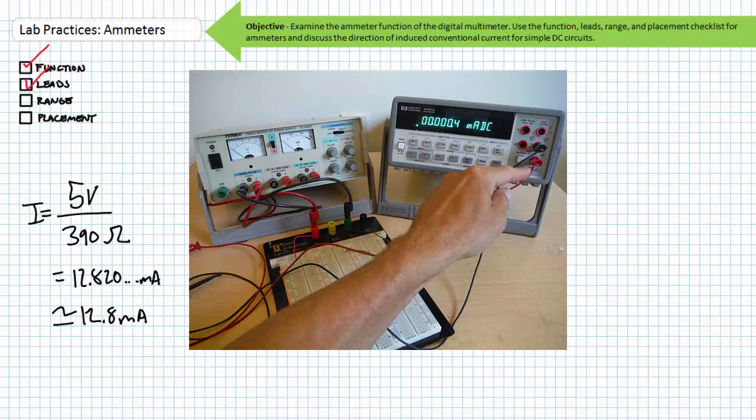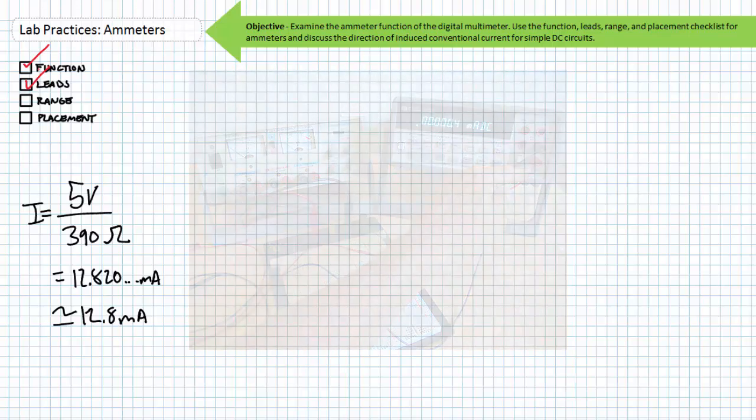Again, notice the DMM in ammeter mode is using different lead placement than our previous discussion of voltmeters and ohmmeters. The HP, similar to the BK Precision, and unlike the Fluke 87, will not tell you that the leads are in the wrong place for a given function, and will sit quietly in the passenger seat as you drive your Lada off the cliff. Don't get mad at the DMM when you're the one in the driver's seat.